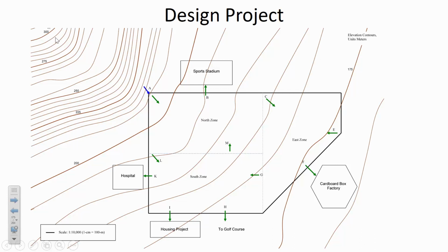But the question you're going to face in this project is, how much water do people use? Because it's easy as an engineer to oversize infrastructure, to make the pipes gigantically large so they'll always be big enough. But the problem with doing that is that it's not efficient and it's not considered optimized. You'd be providing maybe enough pressure, but you wouldn't be doing it economically. The project handout gives an overview of the assignment, and it explains that during the peak flow condition, everywhere in your network has to have at least 240 kilopascals of pressure.